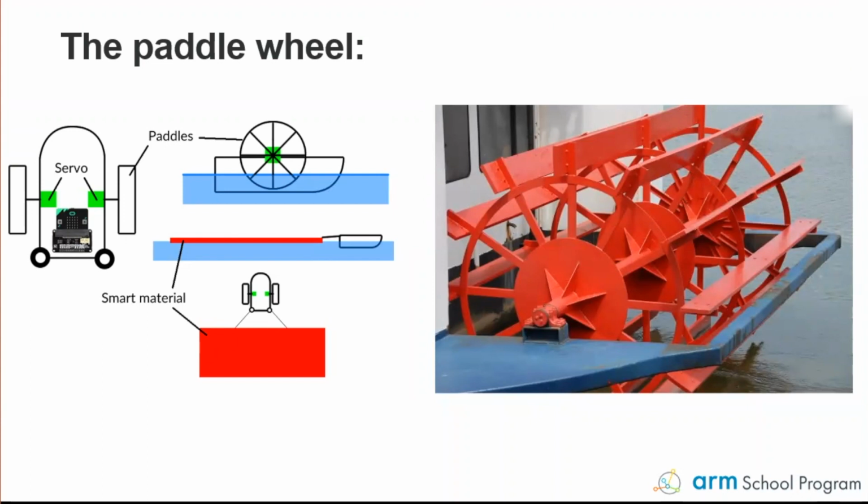And that is probably the hardest bit of this challenge, having an understanding of some of the material science to make the paddles stick to the motor in a way that doesn't just shear off as soon as the motor turns. And this is why getting the motors with the right gear ratios is really important. Like 1 to 298, 296, I can't remember. That one is slow enough that it will move forward slowly, and it won't just shear off at the first, depending on what material you use.